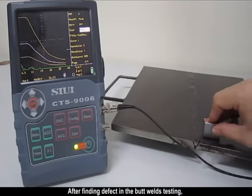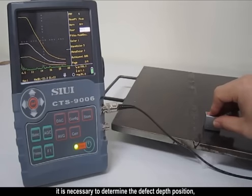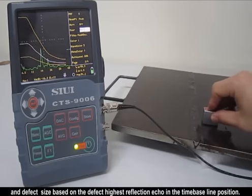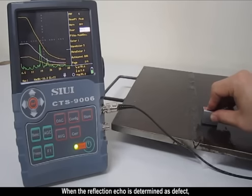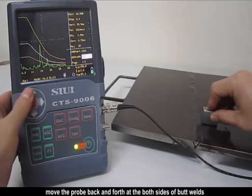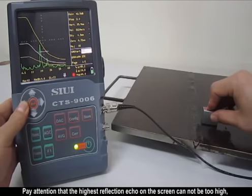After finding a defect in the butt welds testing, it is necessary to determine the defect depth position, the distance between the defect and weld center, and the defect size, based on the defect highest refraction echo in the time baseline position. When the refraction echo is determined as a defect, move the probe back and forth at both sides of the butt welds to get the highest echo of the defect, and adjust again to hit the highest echo.